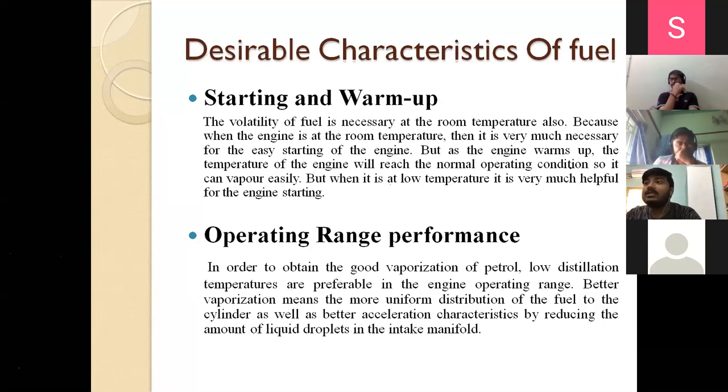As the engine starts warming up, the temperature of the engine is increasing. So the fuel should retain its volatility at the higher temperature also. And whenever the engine is warming up, it should be volatile enough so that the engine can run smoothly.